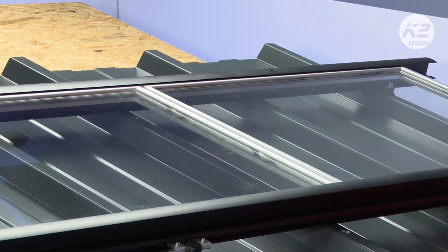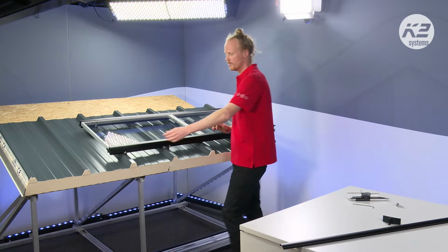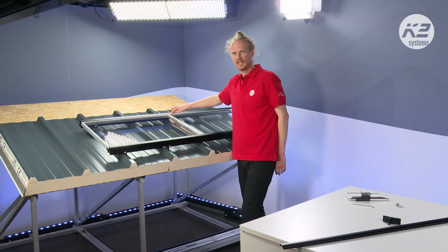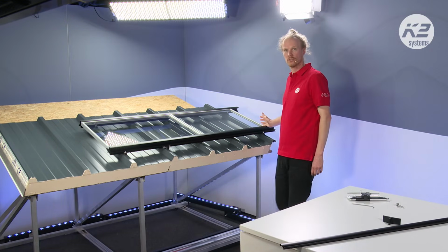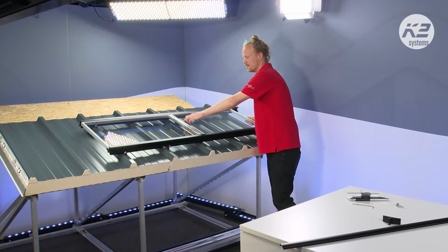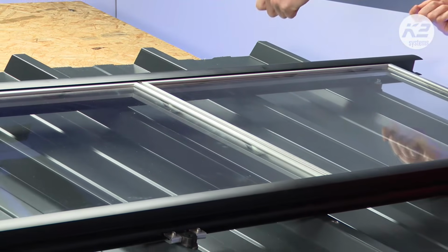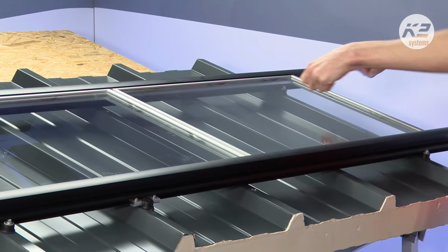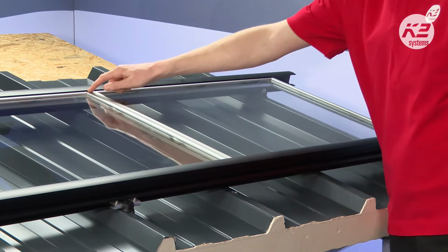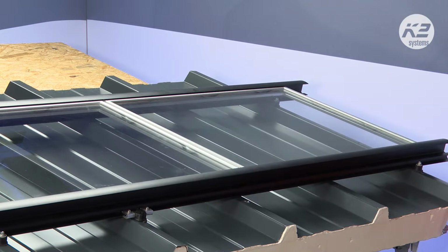And so in some places we've heard the feedback, oh, well, how do you stop people stealing the panels, because they are actually just an up-down process. But once you've got this end stopper in and the safety in the middle, and you've cut your rails on the other end and put your other stop in, it's actually impossible to get this panel out, because you have to take this out first, which is locked in, and you cannot pull the panel up because this stopper is in here as well. And so you're creating a secure setup, more or less.